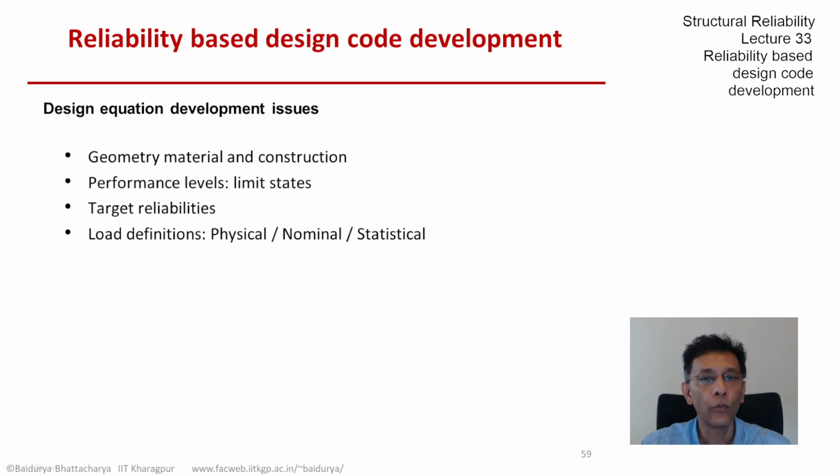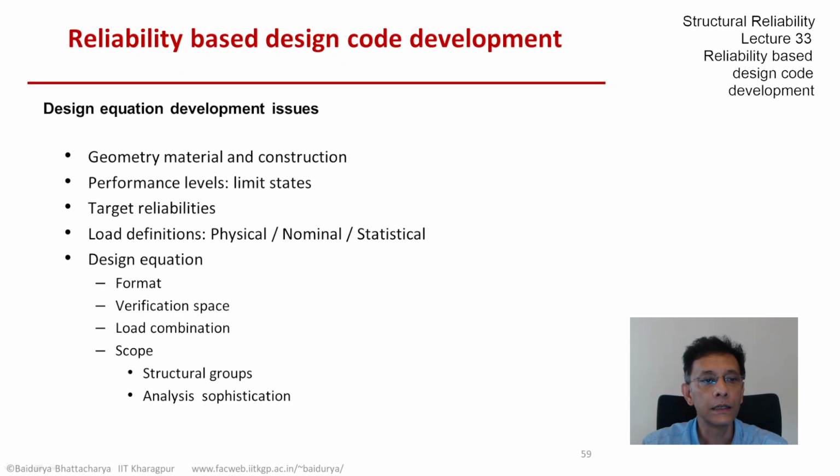Then how our loads are defined. Are we taking a physical definition? Are we talking about nominal loads? Are we talking about statistical description? So these things have to be clearly understood and separated. The design equation itself, what format? There are many equivalent formats, but each will have different outcomes. So we must decide unambiguously what the verification space is. Is it in terms of stress or strain or moments or forces, etc. So we need to make sure that that aspect is well defined.